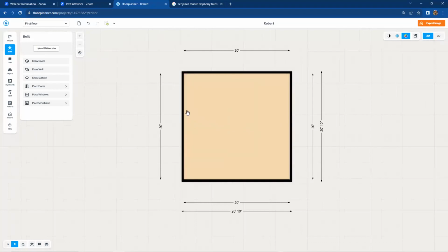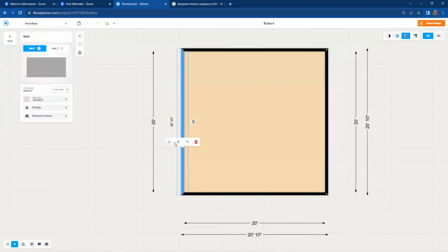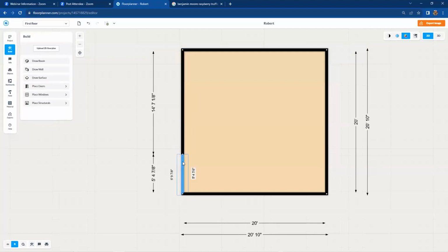To do so, I want to split the wall into two different pieces. You can put your finger anywhere over here or your cursor, left click, and one of the options in there was not just a curve or add a wall, but you can split the wall. Split one piece of wall, the second piece of wall, grab the point in the center there, and you can actually drag that slowly, and it will snap to the center.